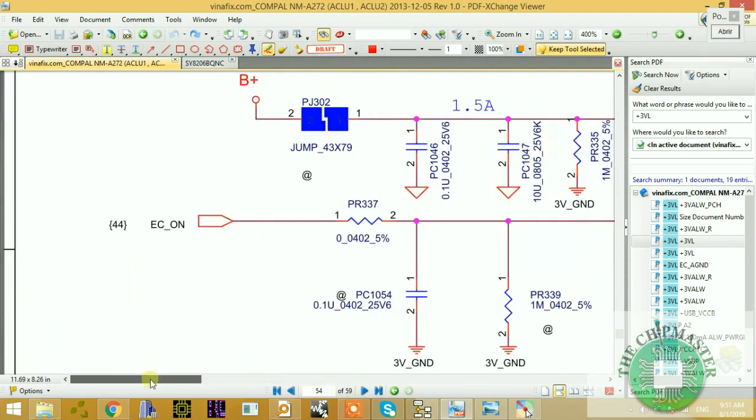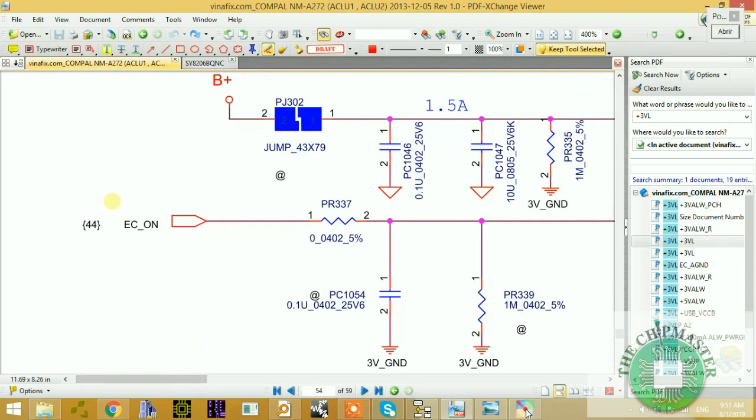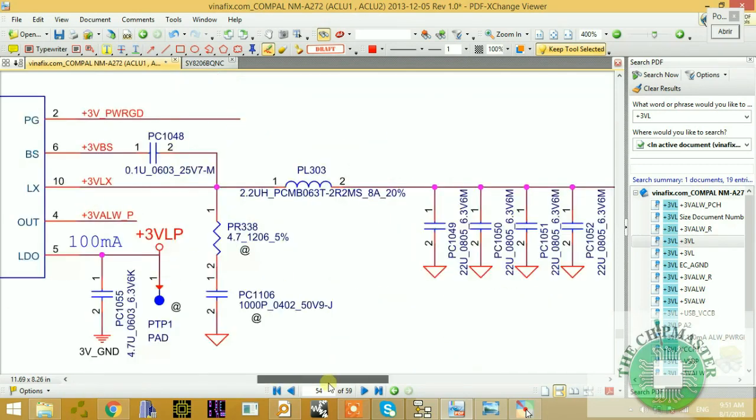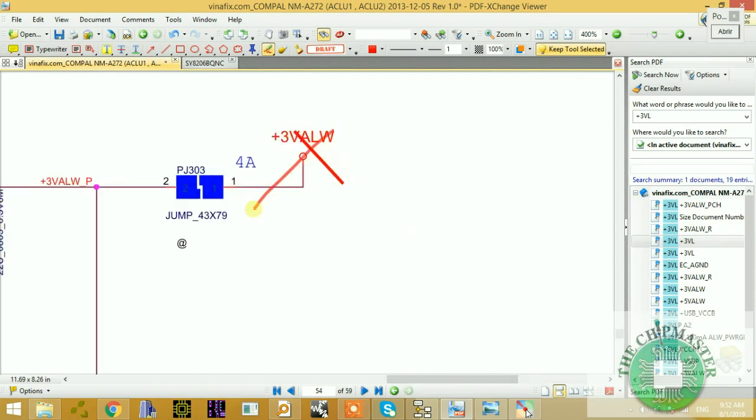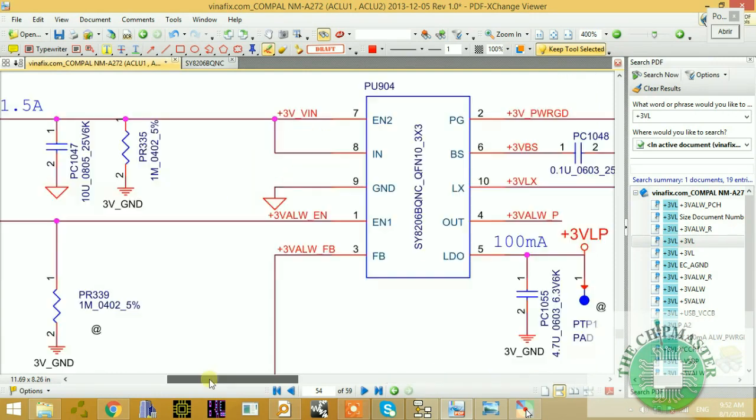Now, many times this fault will happen on a motherboard where the signal does not come. If the signal is not coming, then we should check the working conditions immediately of the IO controller. Suppose the signal is not coming, then this voltage will be dead. No voltage out, no output, because it has not been told to turn on. So this chip will be cut off, right?